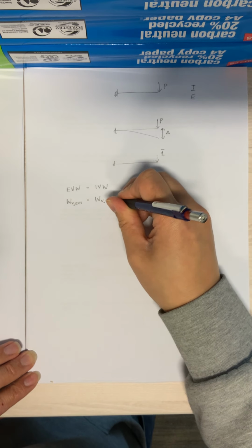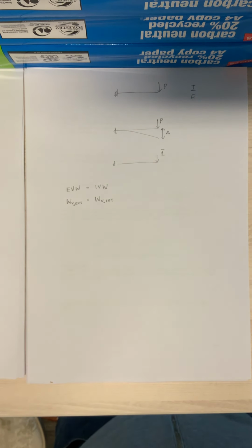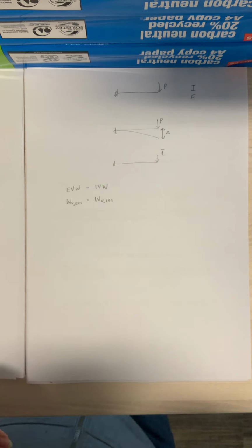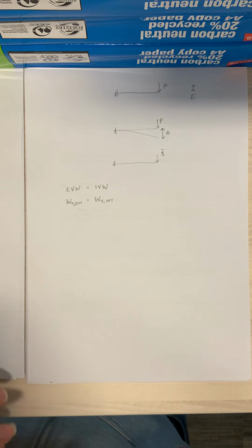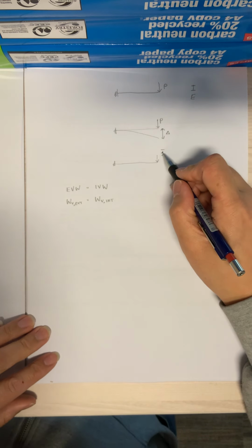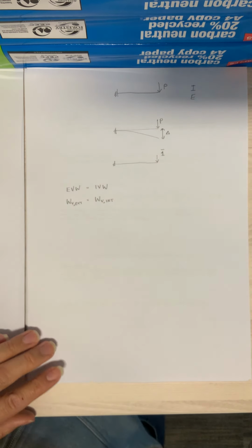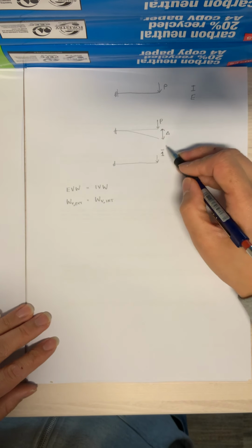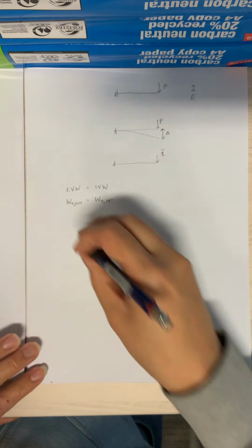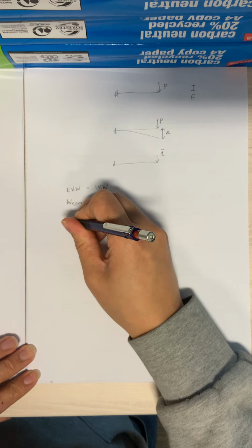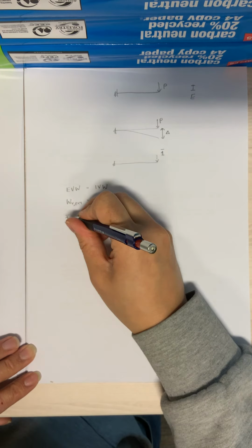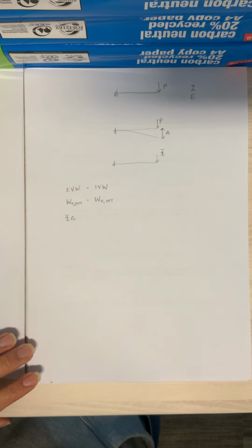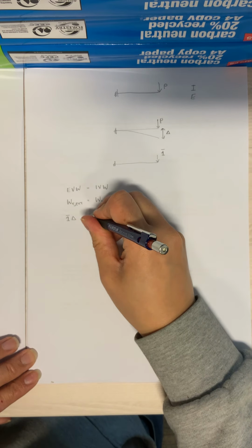So don't worry about the proof. We'll prove why this works later on. So the external virtual work is of course going to be equal to this 1 bar multiplied by delta. So the work done is going to be the 1 bar times the delta. So we'll put the 1 bar, and then we'll put the delta, where the delta is to be calculated.